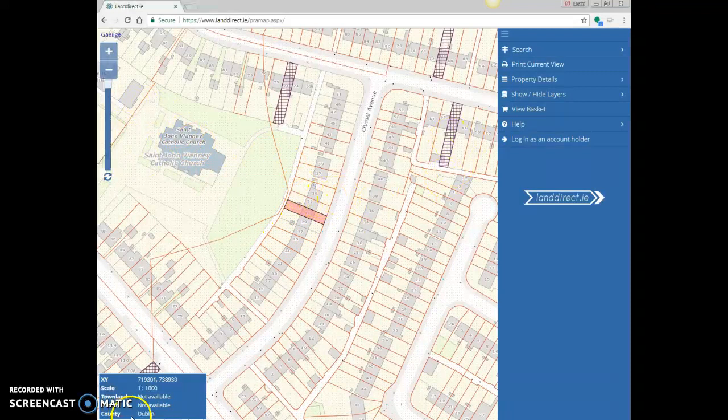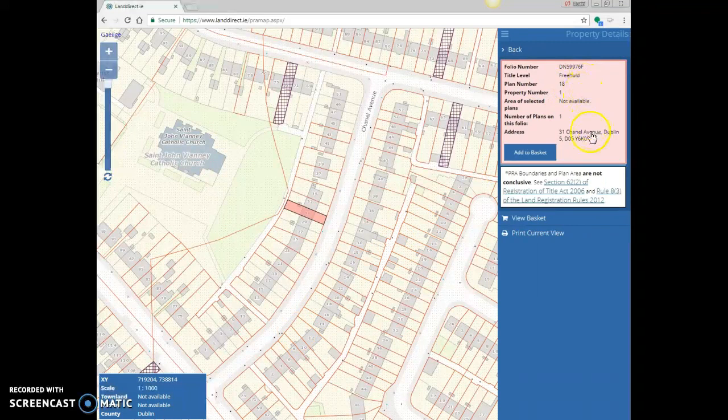Now, what I want to do with the scale bar, previously we had a scale bar on our drawing. This time I'm not going to have a scale bar on my drawing. So this time what I'm going to do is I'm going to use the scale. So when I export it, I'm exporting it as per the scale, and then when I get into AutoCAD, I'm scaling it back up. Okay?